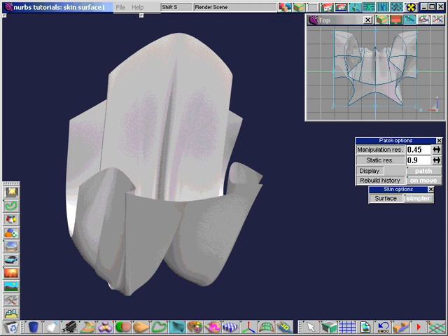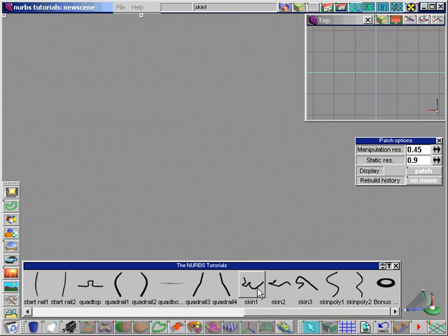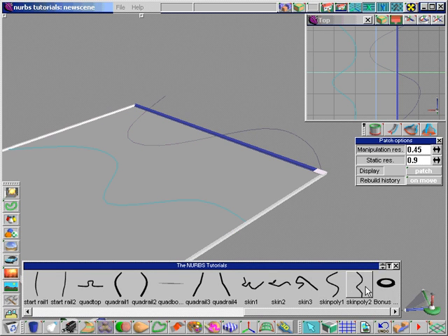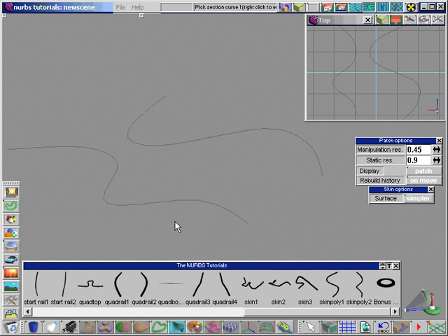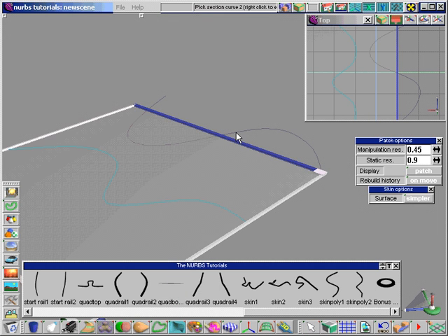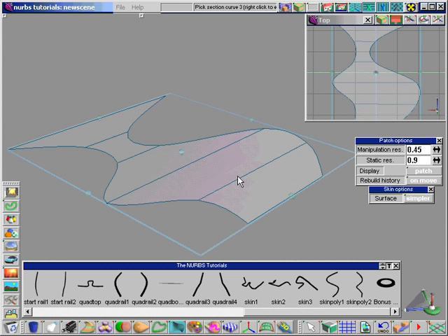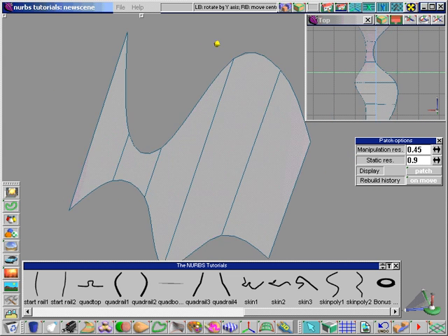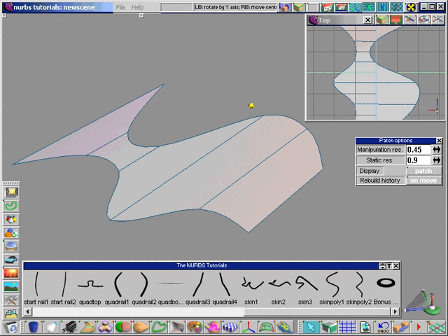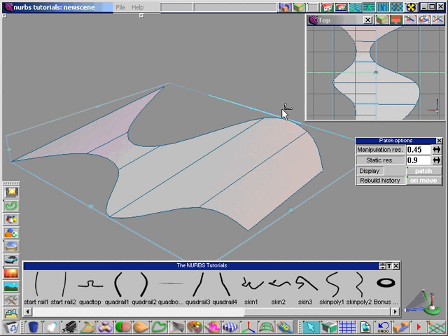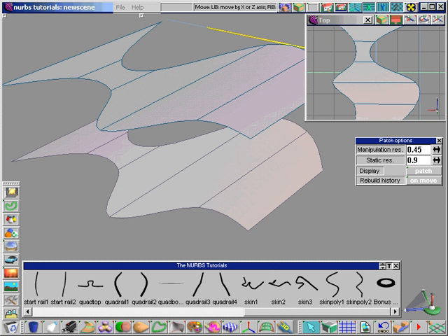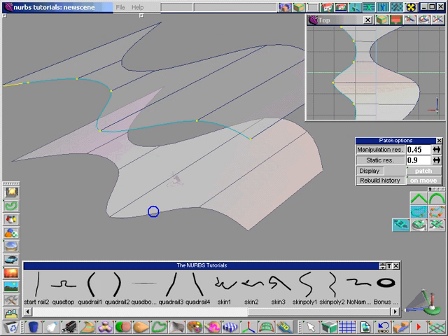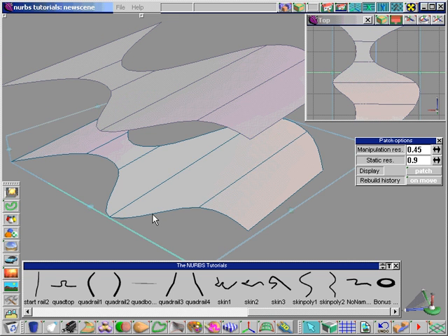We're also able to construct flat NURBS patches and use them as you might in polygonal modeling. Let's skin two curves drawn on the grid. You can see that it's a perfectly flat surface. We'll copy one, raise it up a bit, and use the Curves library again to save precisely positioned source curves, which we can then use to connect the two surfaces.